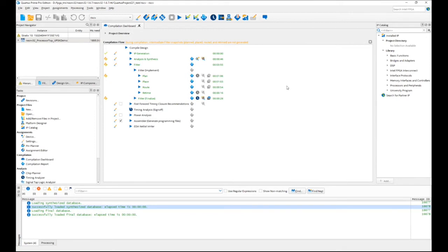The only thing that you would necessarily need a license for in a case like this would be if you wanted to use the IP catalog, and you have to pay for a separate license with that. Otherwise, you should be able to generate everything for those devices, from start to finish, HDL code all the way through the whole fitting process, including timing analyzer. So the fact that you got an error message in timing analyzer saying that a license is required is very curious, and it sounds a lot like there's a bug in the software there.